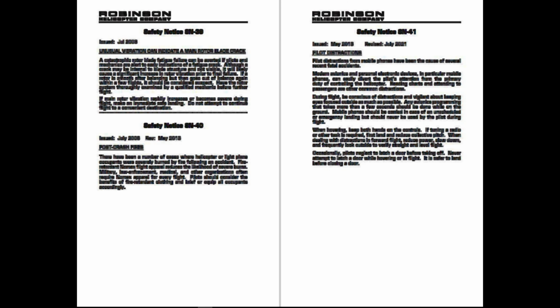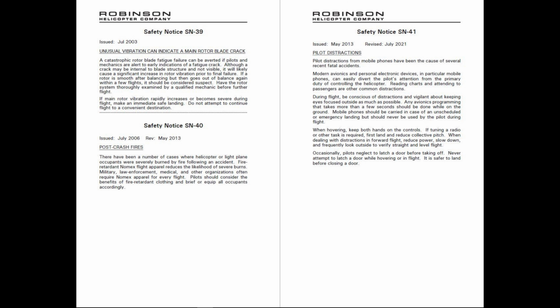While flying, you notice a strong, rapidly increasing, low-frequency vibration. What might be the cause? If rotor vibration rapidly increases, there might be a crack and you should land immediately without going to a convenient destination.